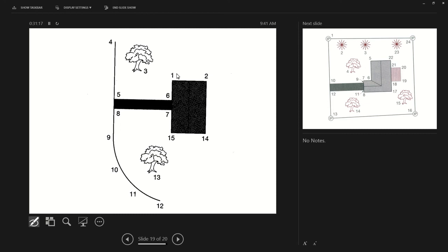Okay, so point one here, if I was to code this, my code would be B, L, D, G, space B. Okay, so that's for point one. That would be my code. So it's building, and I'm going to begin it. All right. So if I go to my point number two, I'm collecting out in the field. This is just going to be B, L, D, G. All right.